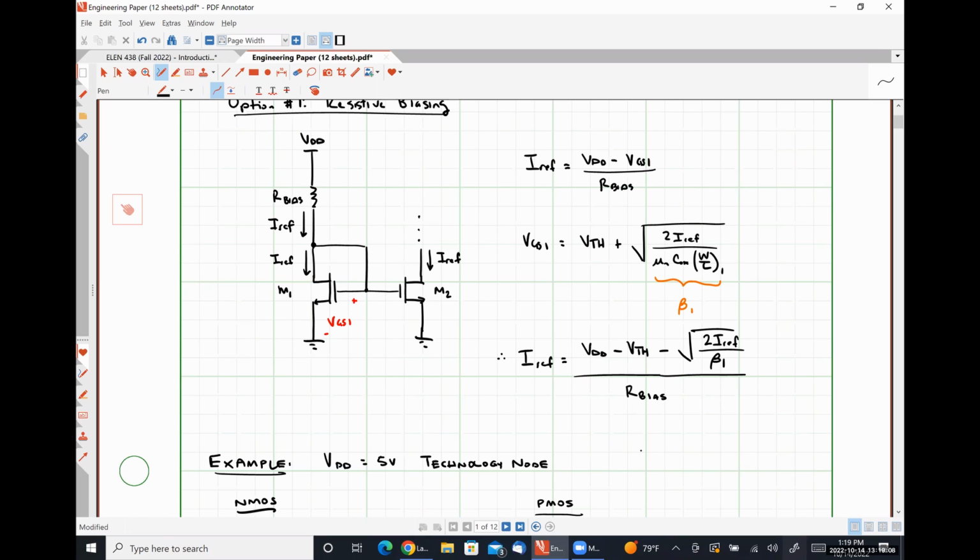That will, to some extent, largely eliminate the temperature dependence because the transistor is going to behave like a transistor. We're going to have some mobility related effects, but that's all happening underneath the square root sign. So it's not a linear relationship. So it's a little bit better.